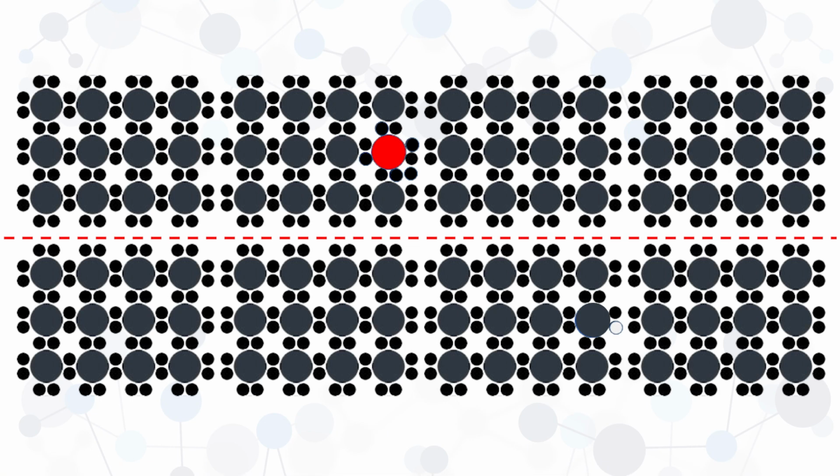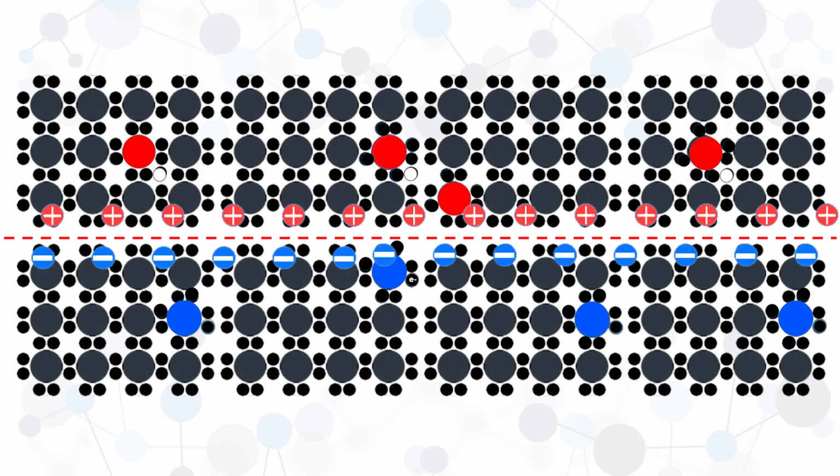Two layers, one N-type and the other P-type, that work together to control the flow of electrons, make a semiconductor more effective. Electrons travel from the N-type region to the P-type region to fill the holes when these regions are brought together. As a result, the boundary between both areas develops an electrical field. Acting as a barrier, the electrical field prevents electrons and holes from recombining, which would lower the solar cell's efficiency.